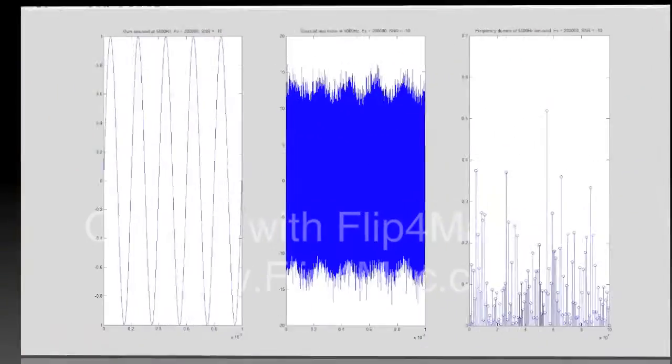One of the main obstacles in our design is being able to distinguish signals of interest from the noise. And one of our main techniques we'll be implementing to do this is increasing the sampling frequency. And as you increase your sampling frequency, you'll effectively see your noise floor reduced, thus being able to pick out your signals of interest more easily.